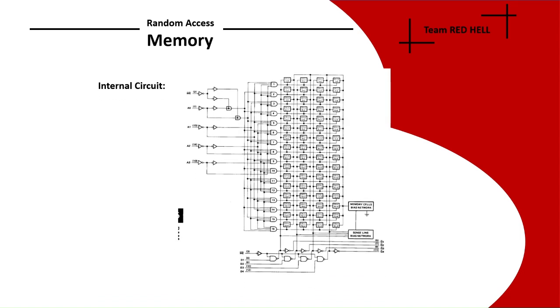And this is the internal circuit of the 7489 IC. It is taken from the datasheet of the IC. So we can see that address inputs A0, A1, A2 and A3 are going through a decoder to the binary cells, and select pin enabling a specific row, whereas disabling the other rows.